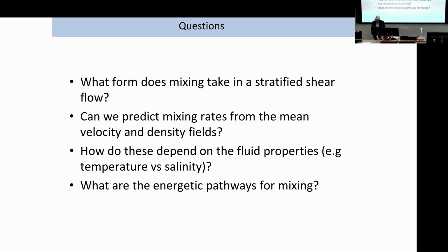So what I want to do in this talk is to address these questions. I want to ask, in what form does mixing take place in a flow which has a stratification and has velocity differences, a shear flow? Can we predict the rates at which these things happen given the mean flows? How do these depend on the fluid properties? Does it matter whether in the ocean, for example, it's temperature we're concerned with or salt, or in a gas, methane or hydrogen? And what are the energetic pathways? How does it actually happen?